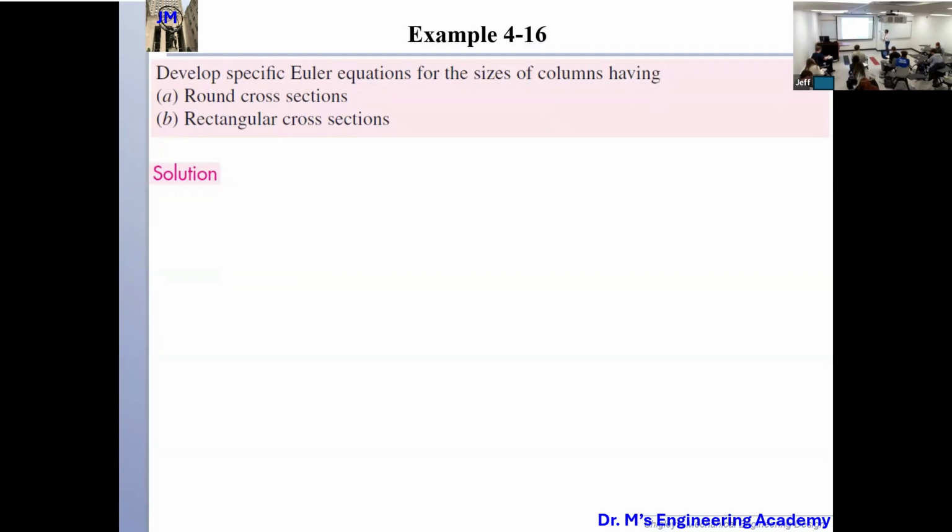So k is D over 4, and you just plug in. You can calculate this D, and plug A into that equation also. And you will have, we can calculate this one as 64 Pcr L squared over pi cubed C multiplied by Young's modulus, to the power 1 over 4.